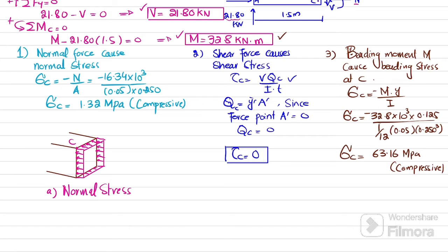The next case is for shear stress. Again, I have to draw the figure like this here. We know that this is your point C. At C, shear stress will be equal to 0. But when you move downward, the shear stress will be like this. This will be the shear flow. We know that shear stress distribution in a rectangular section is parabolic in this web portion. So at point C, the shear stress is 0, but when you move down, shear stress increases and is maximum at the centroidal or neutral axis. So the second case is about shear stress distribution in this rectangular section.